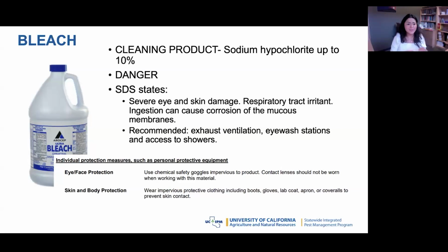And so eye and face protection is recommended. It says here to use chemical safety goggles that are sealed to the face. And it also talks about wearing protective clothing if the person is applying it in a huge amount, even boots, gloves, and coveralls to protect the skin.